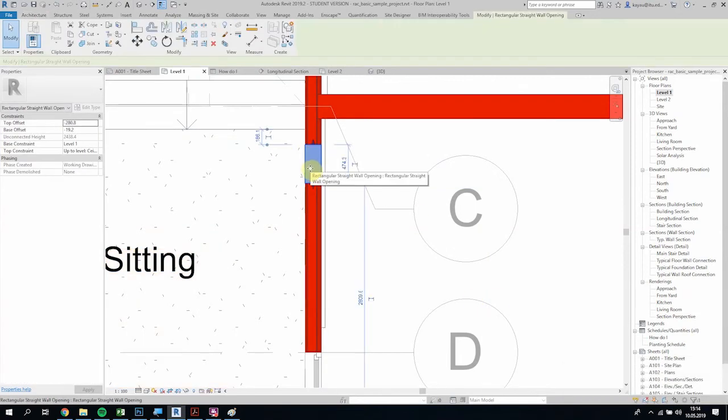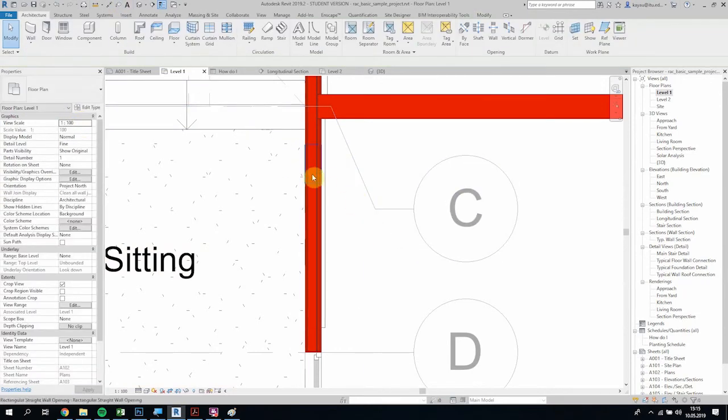Click on the opening again. Then here we are using millimeters in default units now. Type down 1900 millimeters and top offset is minus 300, let's say. And click outside somewhere or escape. You won't see this, but you see the borders.